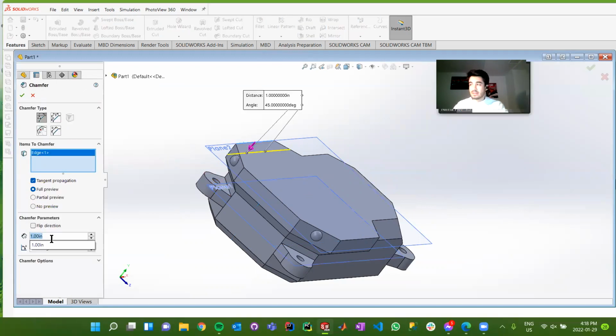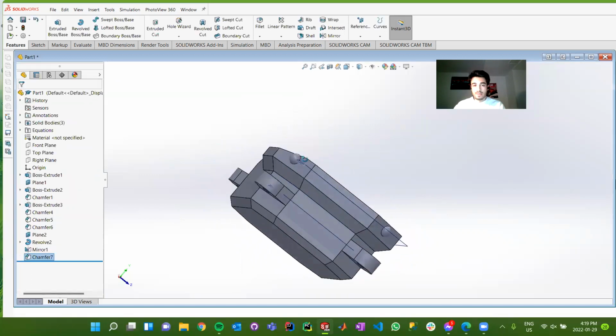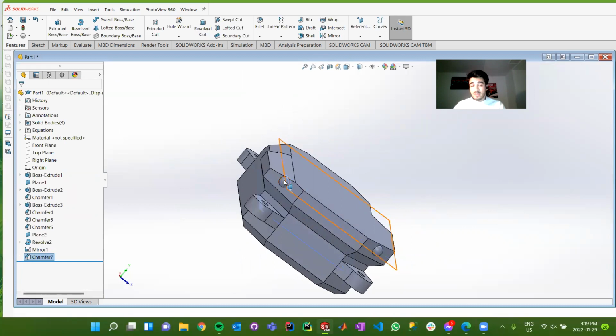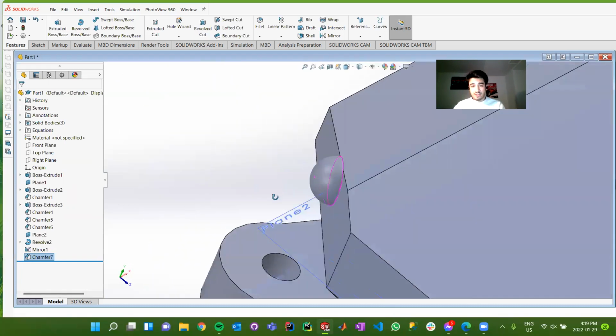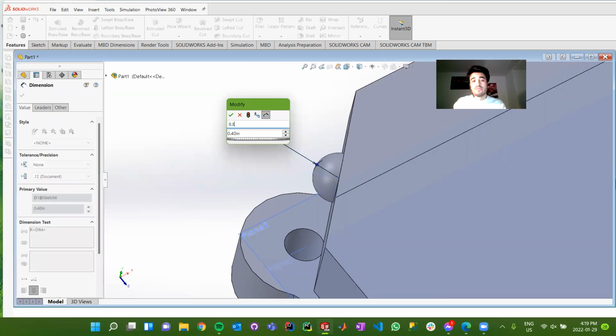And then what we can do is we can click 0.5 for our chamfer length and increase degrees. So as we go further up, you'll notice as soon as we get to 74 degrees, the chamfer essentially stops. So if we press that, that's perfectly fine. We'll actually have to adjust this camera because of the fact that this edge actually isn't perfectly aligned, because I sort of freestyled this component. So that's a very easy component to fix. We just go into our sketch and then you can just change the radius. So let's make this, I don't know, 0.35 inches.